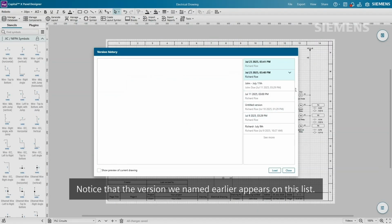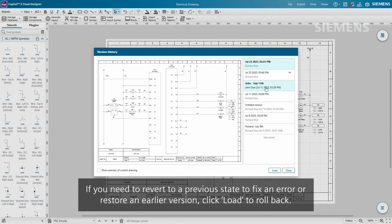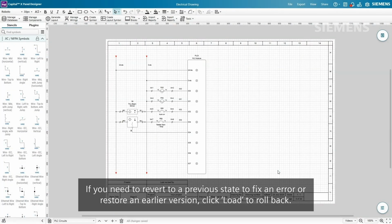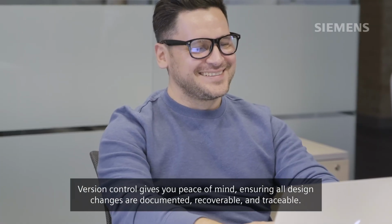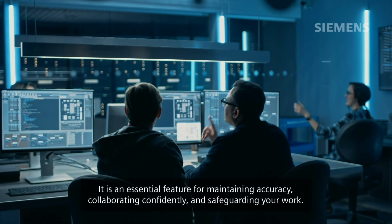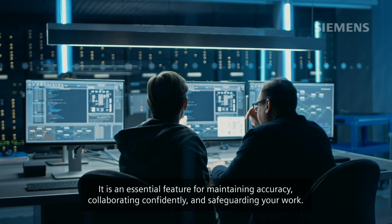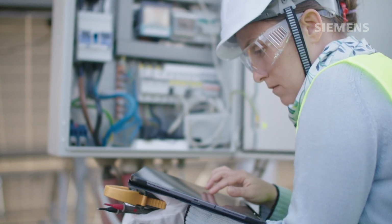You can easily compare different versions with the preview and identify what has changed. Notice that the version we named earlier appears on this list. If you need to revert to a previous state to fix an error or restore an earlier version, click Load to roll back. Version control gives you peace of mind, ensuring all design changes are documented, recoverable, and traceable. It is an essential feature for maintaining accuracy, collaborating confidently, and safeguarding your work.